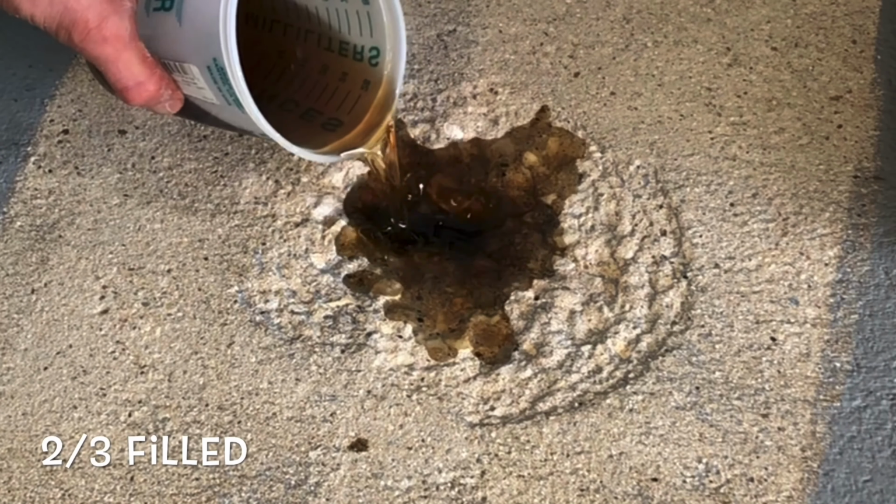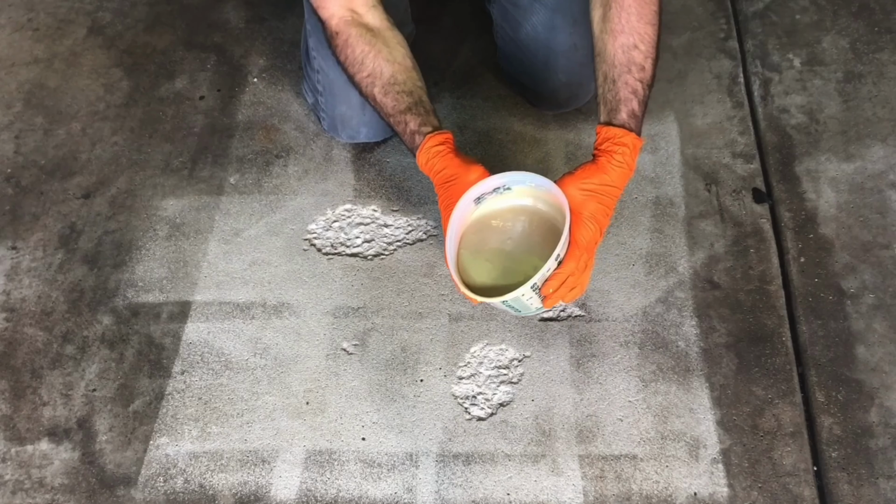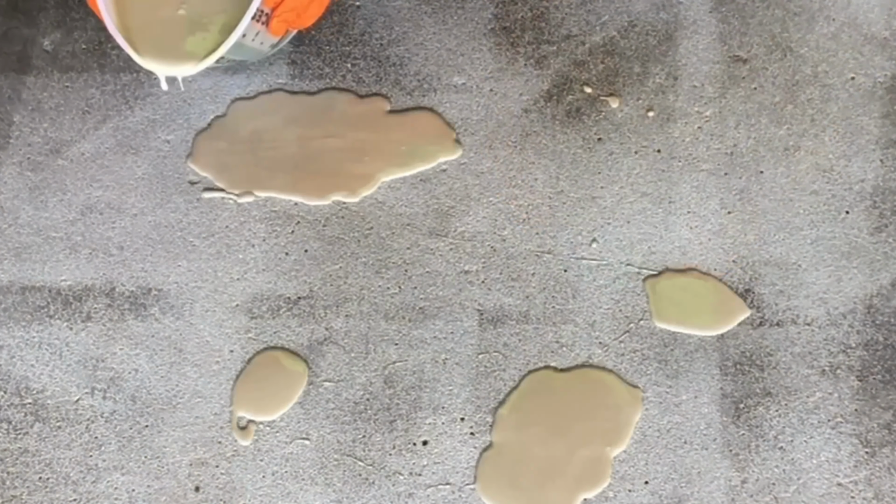Josh, you have any experience with those products that you'd like to add? Yeah, all three of them. When it comes to the PCF 45, it's a nice material because it hardens so quickly. You mix it with sand, or the sand is put down and then it's dumped into the sand because it's very, very thin, like water. And the Polyflex, of course, I've used that as well to do spalls. But again, it's always a matter of what the manufacturer recommends as the product for that application. So I can't stress it enough that if I'm not sure about the area that I'm repairing with a given material, I'd pick up the phone and call the manufacturer.